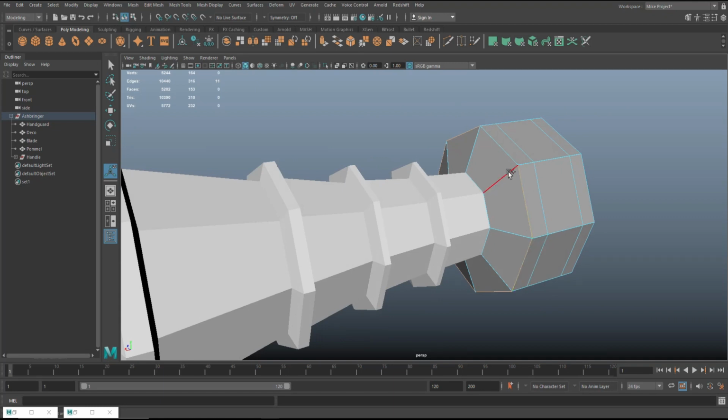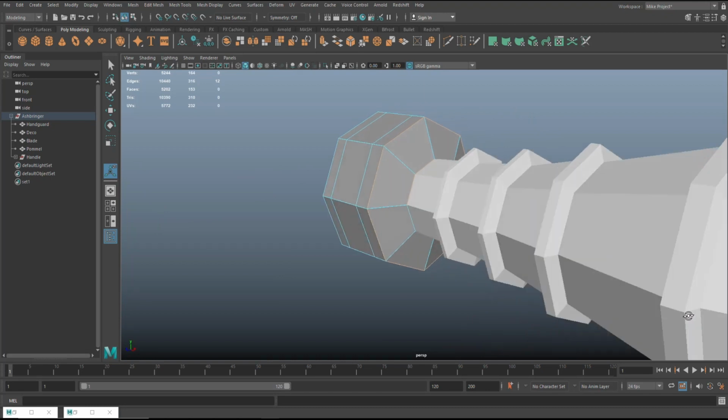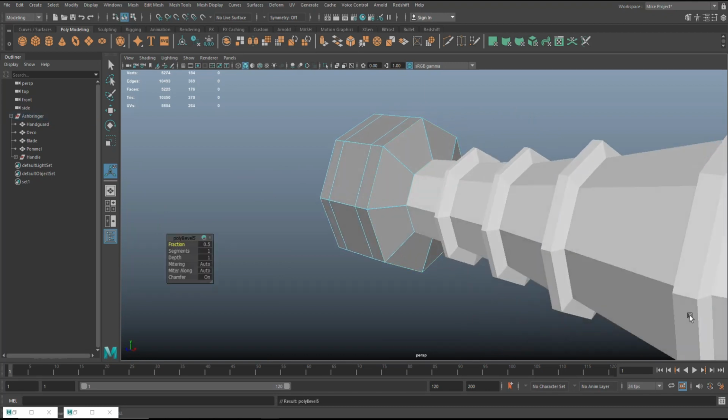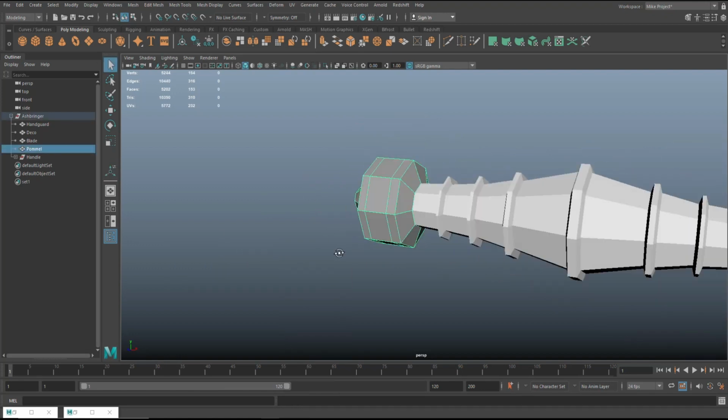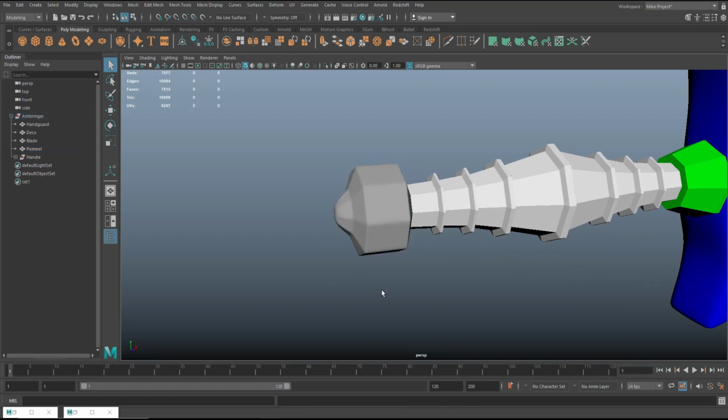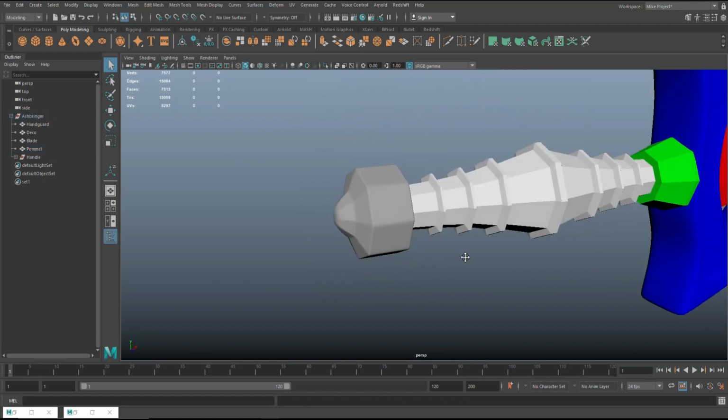And the reason why I have to do that independently right now is because I beveled these guys, so there are tiny gaps there, right? So we're gonna hit Control B, and we're gonna do 0.01 again. Okay, so now if we go in and we do a preview smooth, you see that we still basically have that shape, which looks fine.